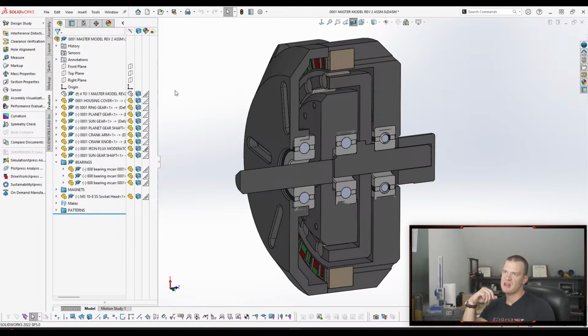I wonder if it's faster, or more lightweight, to have Solidworks take this assembly and insert it multiple times, in each part, and then delete the bodies as a feature. I wonder if that's faster or slower than generating just the geometry that you need in each part. But I can see an advantage of doing the master modeling way where everything is in one location, as opposed to having the sketches be technically in a separate document.